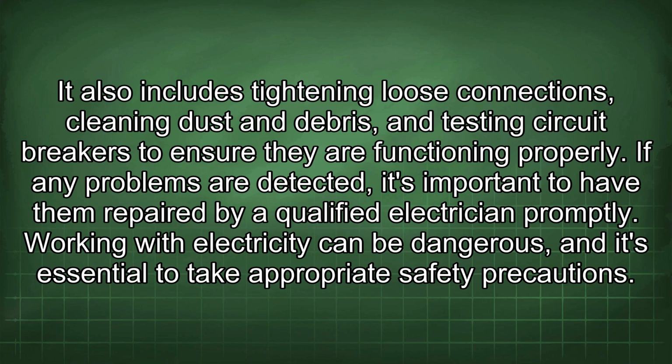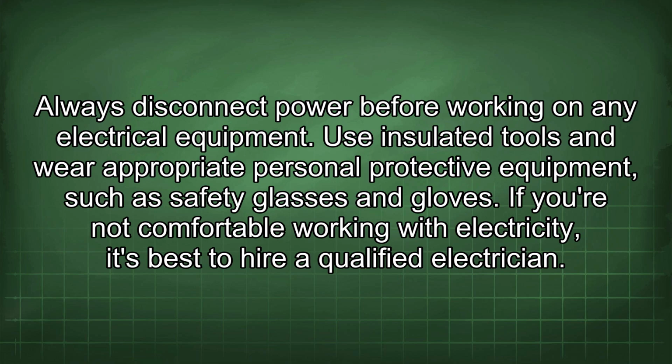Working with electricity can be dangerous, and it's essential to take appropriate safety precautions. Always disconnect power before working on any electrical equipment. Use insulated tools and wear appropriate personal protective equipment, such as safety glasses and gloves. If you're not comfortable working with electricity, it's best to hire a qualified electrician.